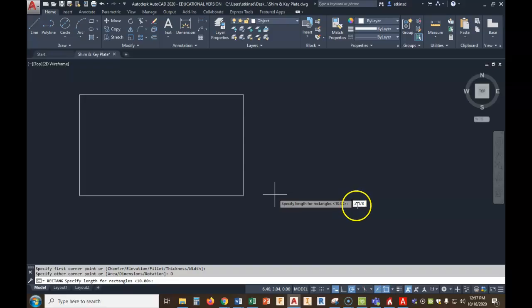We have to have the dash between the whole number and the fraction. Otherwise, it wants to say 21/8. Okay, and you can't put a space. So either one's fine. So I'm going to hit enter. And now it's asking for my other dimension. So it asked for length, now it's asking for width.